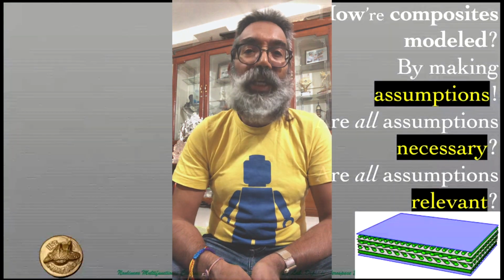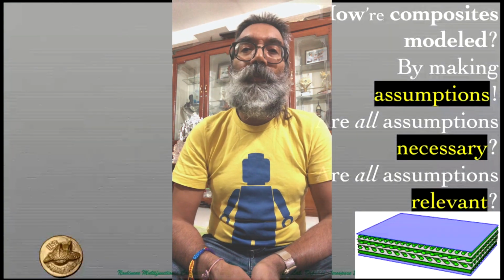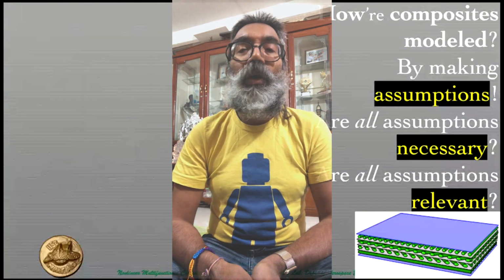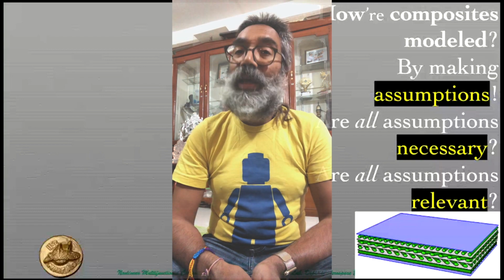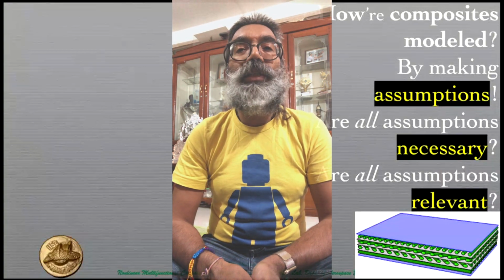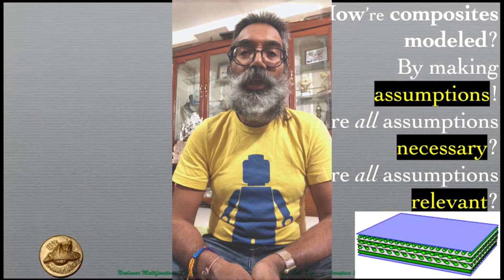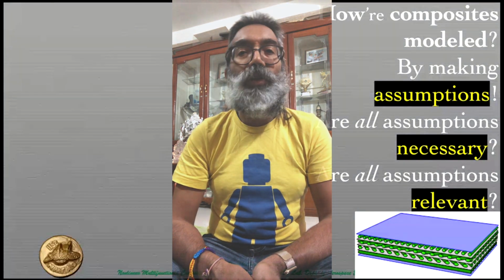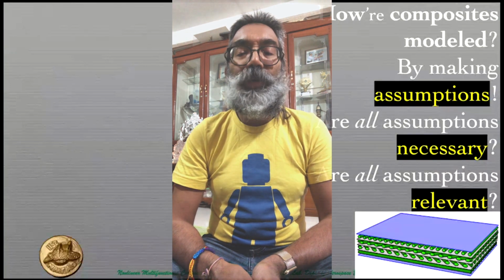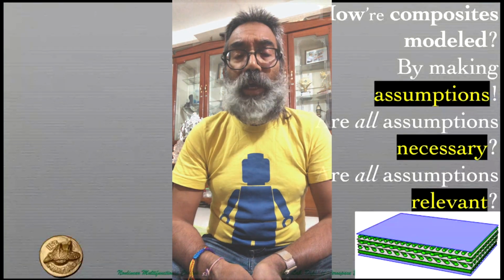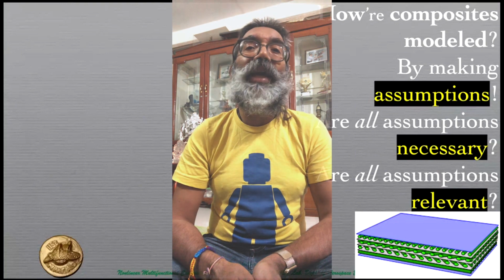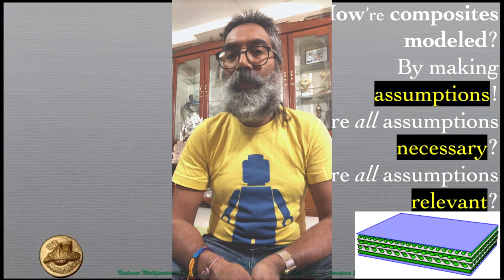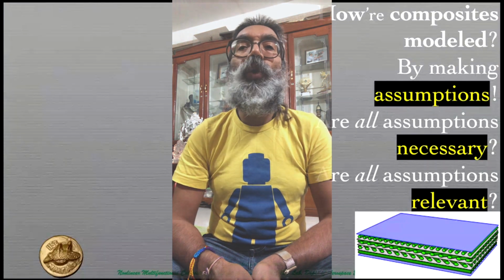So that's where you have a beam or a column or a rod, or you have a shaft. All of these are examples, or even an element of a truss, an element of a frame. All of these are one-dimensional structures where the cross-sectional dimensions are overwhelmed by the length dimension of that rod or column, whatever you have. So if you call that dimension, let's say, x1, along the length of that rod or truss element or frame element, then x1 becomes the only independent variable.